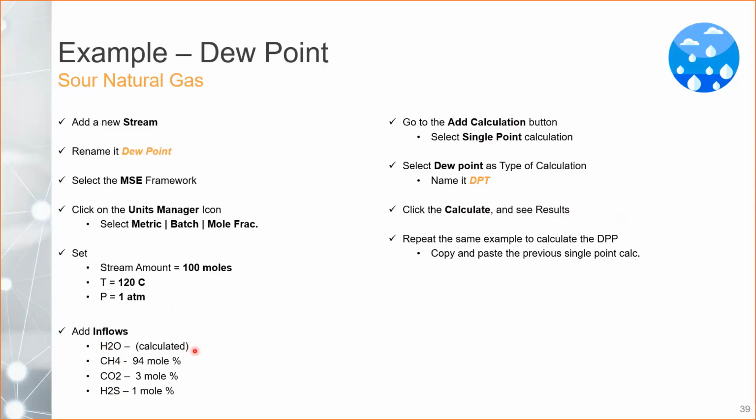When this water condenses, it brings some of these gases, which dissolve into the water and reduce the pH. That can be detrimental for metallic materials, so we want to evaluate the pH of that condensed phase to determine how aggressive it will be for our materials.